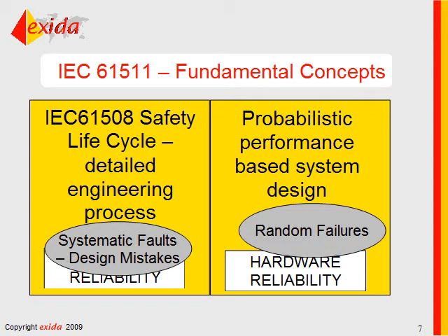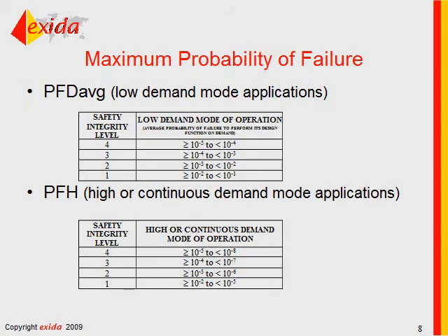You have to come up with your own solution. With any advantage, there are obviously disadvantages, but as long as you can demonstrate that your solution is safe, you can implement that. So if you want to use wireless technology in a safety instrumented system, no problem, as long as you can demonstrate that it is safe enough. And typically that will mean if you lose communications that you go to a safe state.